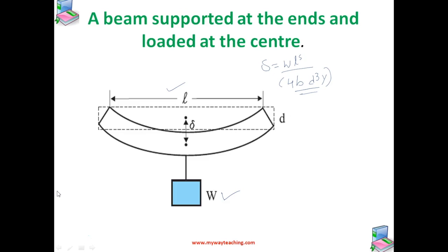Even this relation can be derived using the calculus method. In order to reduce the bending for a given load, one should use a material with a large Young's modulus. For a given material, increasing the depth rather than the breadth is more effective in reducing the bending, since the sag delta is proportional to d raised to minus 3 and only to b raised to minus 1, and the length L of the span should be as small as possible. But on increasing the depth, unless the load is exactly at the right place, the deep bar may bend. The deep bar can also bend.